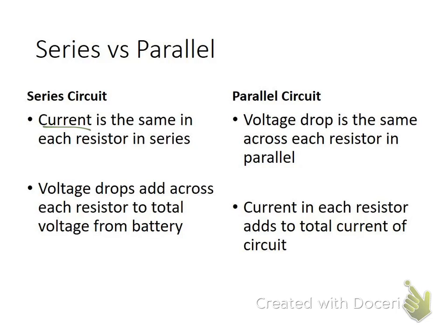The current has to be the same for each resistor in series because there's nowhere else for that current to go. Current is the flow of charge over time. The same charges that go through one resistor go through the next one if those resistors are in series with each other. You don't add these currents up, you don't subtract them away, it's just the same. Now, voltage drop, however, is going to have to add up to the total across every little bit in series. Because for each path, the voltage gained is the voltage dropped.